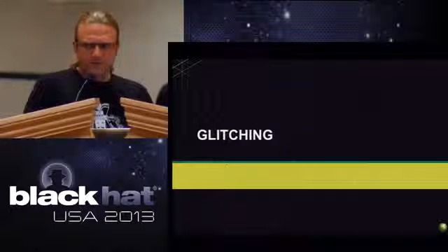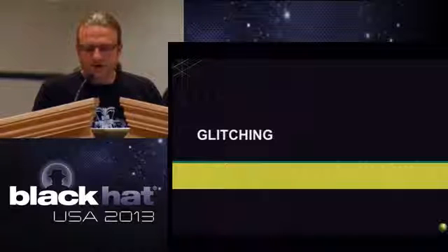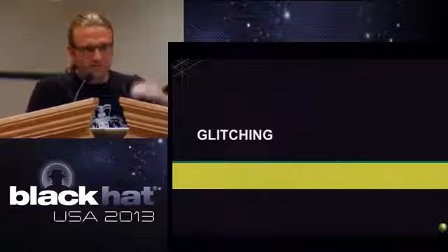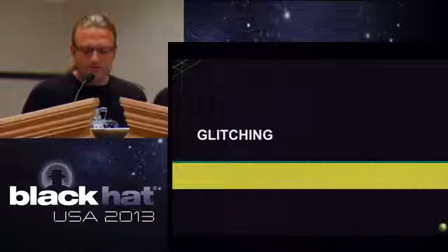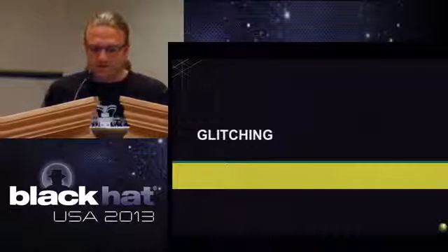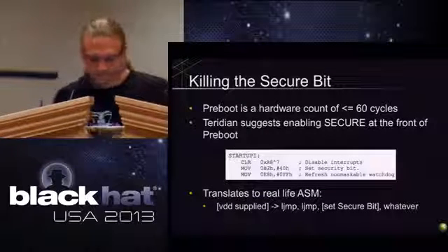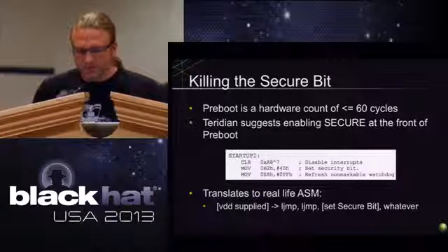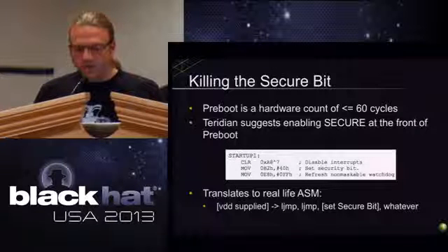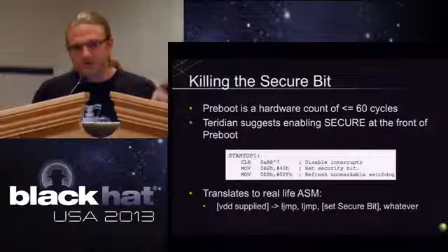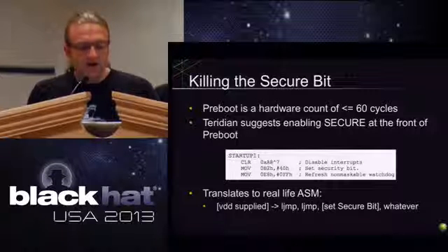But we wanted to do something a little sexier, and it was one of the reasons we're not releasing the GoodFet code, because we went tangential down this path and the GoodFet just couldn't quite keep up with where we wanted to go. We will get there and release it hopefully at some point. So we've got that pre-boot that is like 60 cycles, and in that 60 cycles somewhere that security bit gets set. We just need to keep that security bit from getting set.